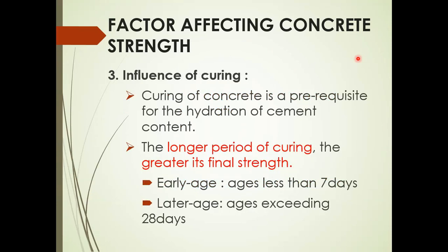And then the influence of curing. Curing of concrete is a prerequisite for the hydration of the cement content. So the longer the period of curing, the greater its final strength. In curing, we have early stage and later stage. Basically, if we cure for about 7 days, it may be enough for us to get the strength, or we can cure for 28 days for better concrete strength.